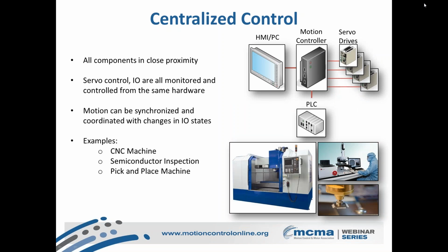So having everything in that central location makes the extended wiring of an analog system much simpler to deal with, and also less susceptible to noise, because typically they're, for lack of a better term, all wrapped in a big metal box and shielded from external EMI. And since everything is physically close, it's all analog and these low-level digital signals, the latency is low. So again, that keyword coordination, you can coordinate I/O to motion.